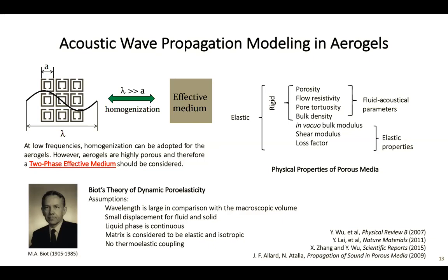And since the aerogel is a two-phase material, we can consider a solid skeleton filled with air. We adopted a poroelastic model for this purpose. One of the pioneers in poroelasticity is Biot, and in his theory, basically all the assumptions that we need to use for aerogels are fulfilled, including wavelengths that should be larger than the macroscopic volume.